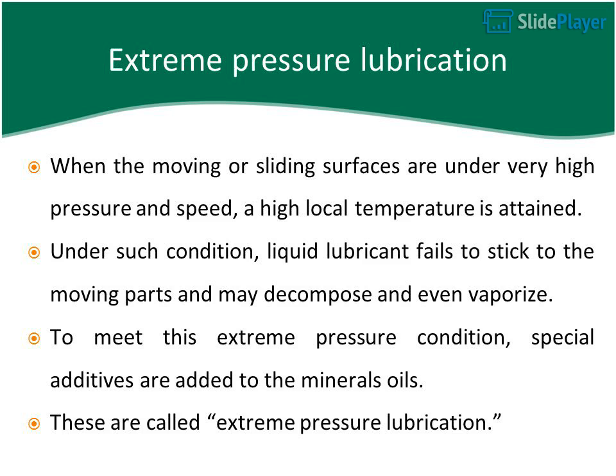Extreme pressure lubrication. When the moving or sliding surfaces are under very high pressure and speed, a high local temperature is attained. Under such conditions, liquid lubricant fails to stick to the moving parts and may decompose and even vaporize. To meet this extreme pressure condition, special additives are added to the mineral oils. These are called extreme pressure lubricants.